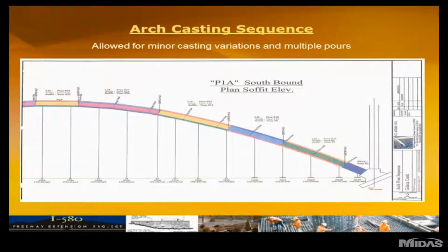Schematic the contractor drew up for the concrete pours, basically a symmetrical type pouring from either side of the arch springings. As you can see, the different colors highlight the various lengths and extremities of the bottom slab, the stem walls, and the lid pours. So many different pours. I think there was about 35 different pours total. So the casting sequence was quite extensive.